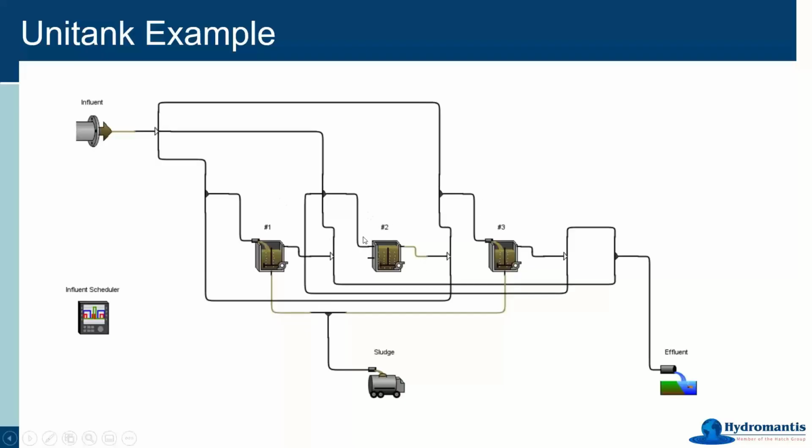As the sequencing happens, it will flip back and forth between those 2 sides. And same thing here, so that the effluent coming off of this can be sent the other way around as well. So basically, you need something that's going to control all of these things, splitting the flow the right way, controlling these splitters back and forth, and then controlling the sequencing operation of all these 3 things.